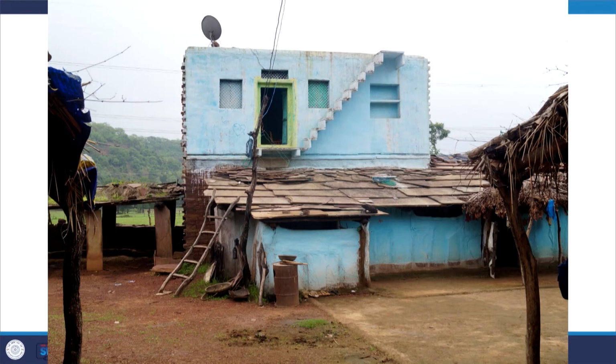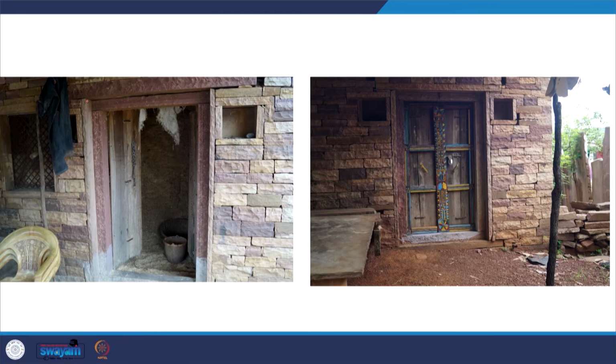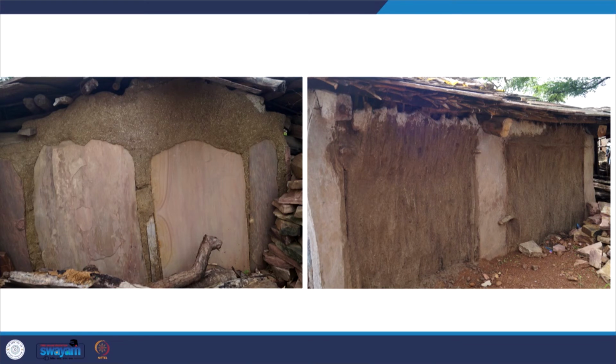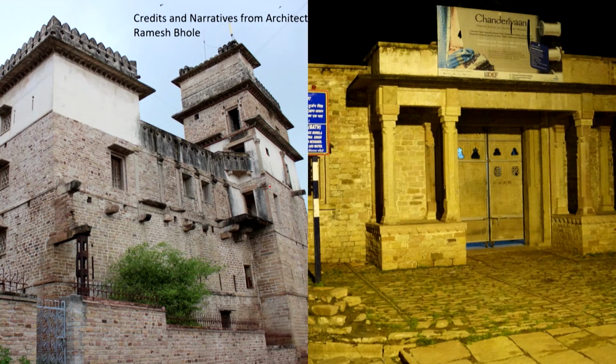So here are some photographs. Even the first floor, they have G+1 floors completely made out of stone. And entrances, how the jambs were created, how they have these cultural aspects, how they create entrances, and the lintels, completely stone lintels, and the renders. If they want to construct a cattle shed, then for thermal comfort purposes, they render the whole wall. So we can see that the local knowledge plays an important role.